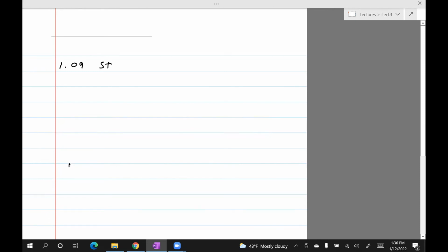1.09 Stress and strength. Okay, so I think we've used both these quantities before, but we've not really thought too much about what they mean in case of materials. They have the same units, but they actually mean two different things. Stress is, as we know, force per unit area, and so is strength. It's force per unit area.